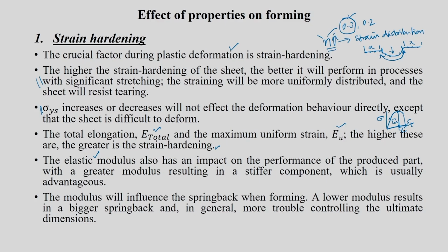Then comes the elastic modulus. Young's modulus can also impact the performance. Mainly, the greater the modulus, the stiffer the component is to deform, which is usually advantageous. This modulus will also affect spring back, which I was discussing with you yesterday. Spring back is the recovery of some dimensions once you remove the load, because of elastic properties. One important property is Young's modulus.